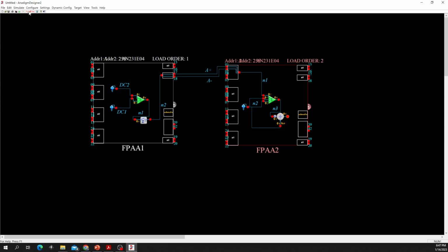Then from here, go to Simulate, Set Up Simulation. Oh, before that, we also need a probe. From here, create an oscilloscope probe. Let's add one here. The output is a bit weird since it's only valid on phase one. I would like to have a much better output, so I will use a sample and hold to get a continuous output that is valid for both phases. Let's add one more oscilloscope probe and put it here.